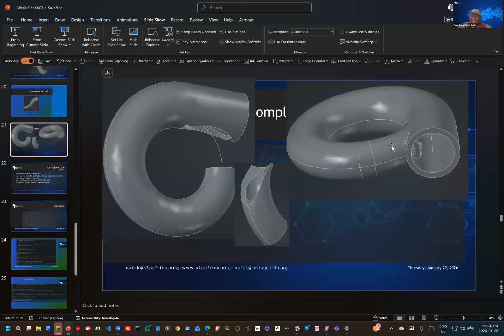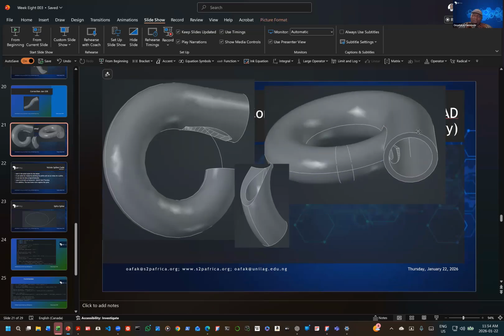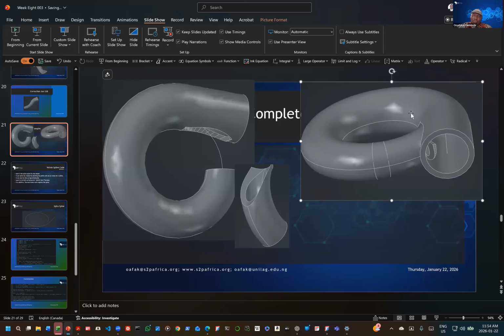You have the file here, so you can look at it from all angles. You can see that the centers enter each other. Now, what we want is to add an impeller to this. To add an impeller, we have to cut the central area completely open, and I want you to do that. Suppose you already have this, made up of this and this. What you are supposed to do now is to cut the inside open.